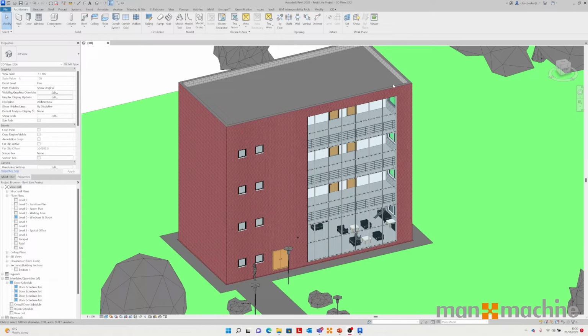So there's a variety of different tools that I want to look at today. And the first one that we're going to cover off is IFC. So when we're working with building information modeling workflows using Revit, the likelihood is that at some point you're going to be asked to produce an IFC file, an Industry Foundation Class file. This is an open format file that is a text-based file that will work on, generally speaking, any of the major BIM interoperability or BIM building information modeling authoring tools out there for reference.